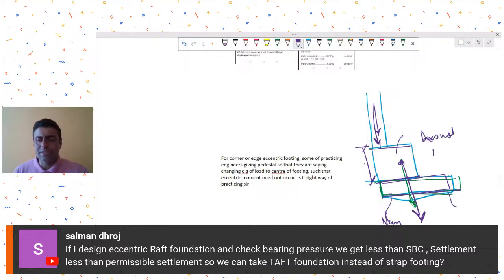Then how does it work on site? Because there are a lot of different issues which we don't consider usually. There is always support from the adjacent plot. That means adjacent plots have some footings. We also have a lot of safety margin in the safe bearing capacity that is given to us. So there are a lot of these margins which help these footings work, but maths wise or physics wise it does not add up, you cannot solve it.